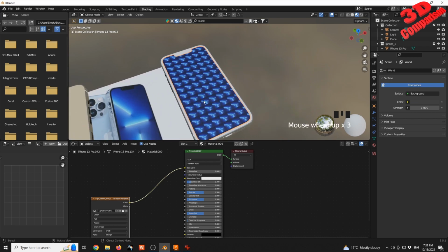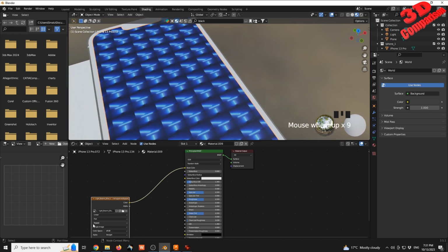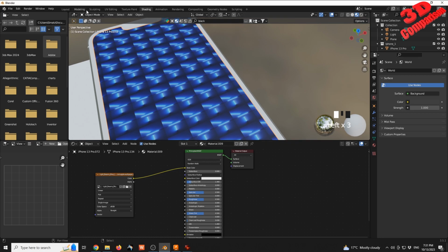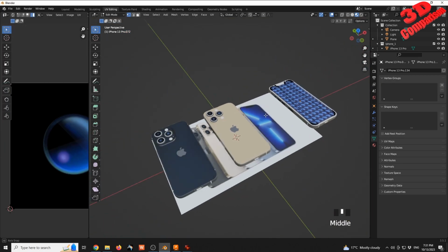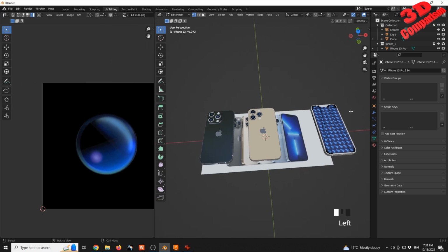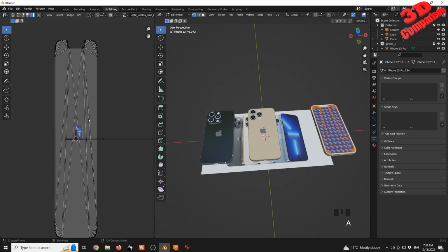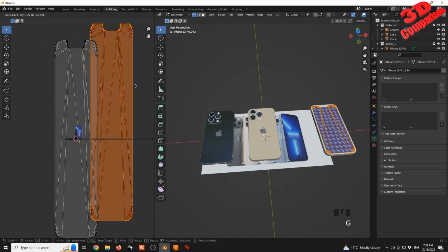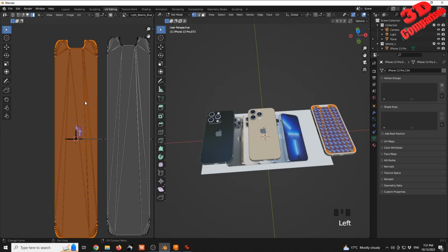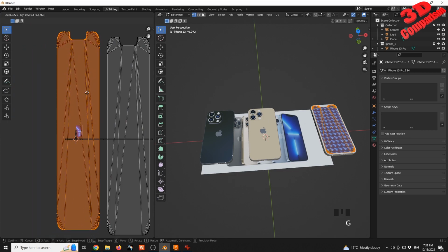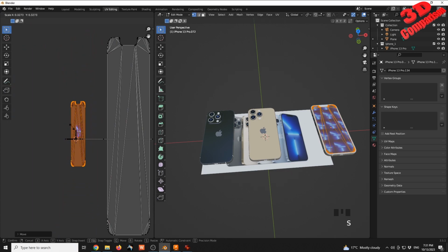And as you're gonna see, this will repeat multiple times over here, since this is set to linear, flat, and also repeat. This won't affect us because we are gonna go back to UV editing, and we're gonna press A to select everything regarding that screen. And we're just gonna need to adjust this over there. So I'm gonna select this. If I move it, this will be the island that will influence the texture. So have that scaled.